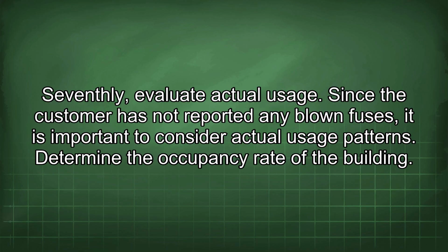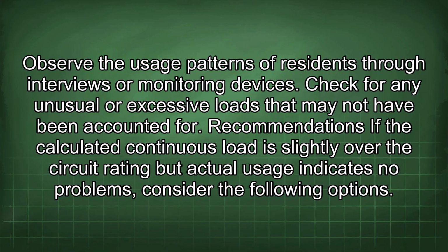Seventhly, evaluate actual usage. Since the customer has not reported any blown fuses, it is important to consider actual usage patterns. Determine the occupancy rate of the building. Observe the usage patterns of residents through interviews or monitoring devices. Check for any unusual or excessive loads that may not have been accounted for.